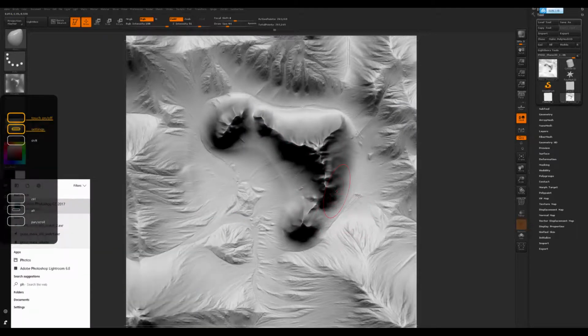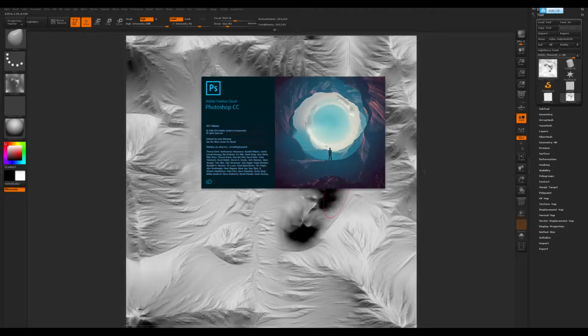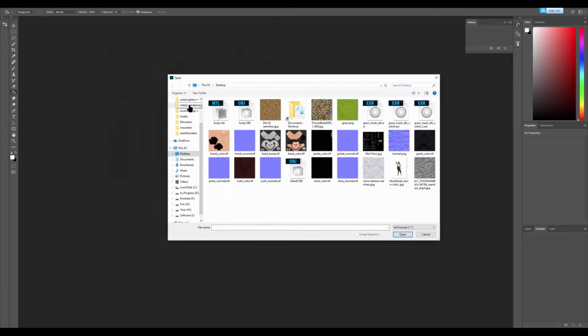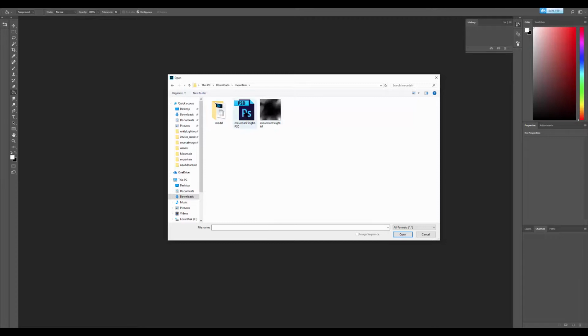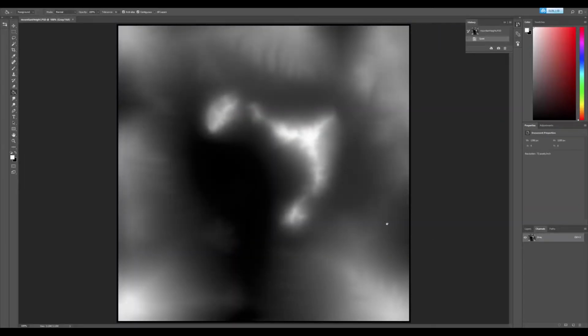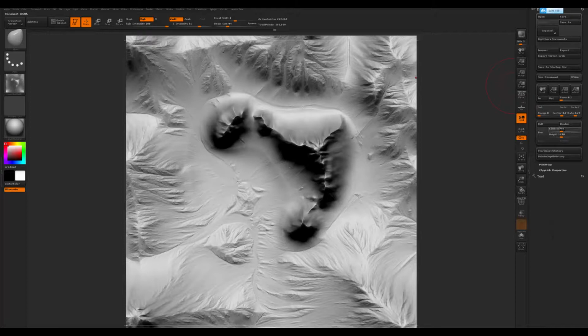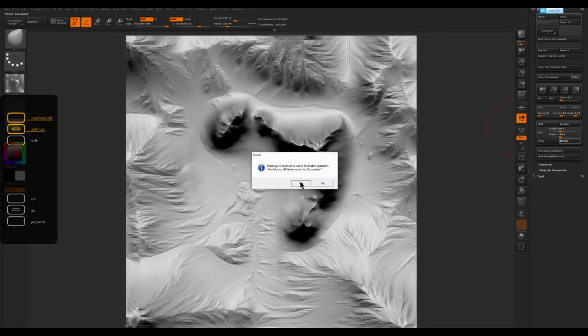And then you want to open Photoshop and to actually convert it into a format that game engine can read, which is a raw format. Let me double click and then go to my PSD file, open it. So what I'm going to do is convert this into a raw information. I have some edge there. I think that's because my resolution is not good enough. My document size is set too big. My monitor resolution cannot handle that. So I'm gonna go down resolution a little bit by going to document and then change the width to 1K instead of 1280. It doesn't really make that much difference. So making sure you get a map that is having no edge.